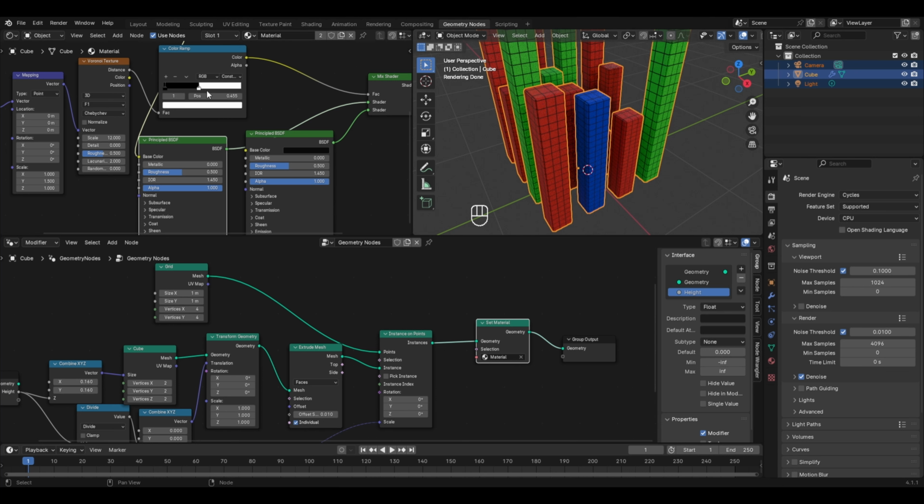And as I told you before, you can change the thickness of these borders or simply these lines with the help of this color ramp. So if I take the second pointer and move it like this, the thickness or the width will basically change. But I think that this much is fine, and you can even change other things like to make them look metallic. You can increase the metallic nature from here or make them look rough from here. So you can try to change these different settings to change the material of the windows or the rest of the building.